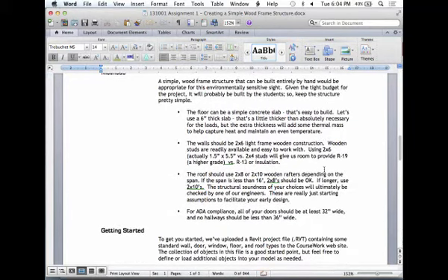In terms of the construction methods, if you've never really worked with wood frame construction, let me give you the briefest of primers in terms of how it typically goes. For a very small building like this, it's very common that we put things on a concrete slab of some type, as opposed to building them up. We could build it up on a foundation and have a crawl space. But for a simple building, we'll often put it on some sort of concrete slab. So we'll have some sort of earth, and on top of that, we'll place some sort of concrete slab.